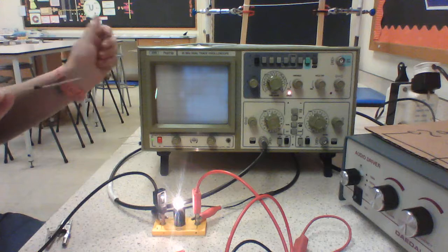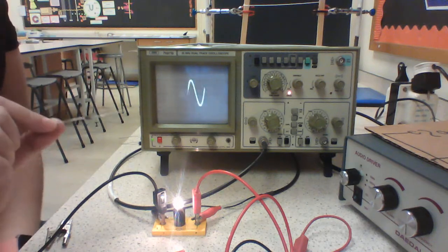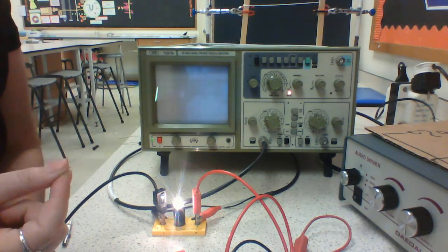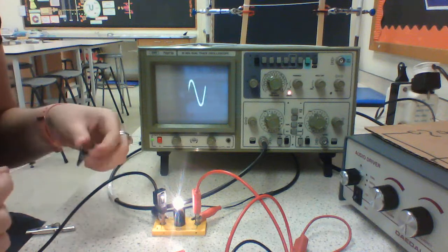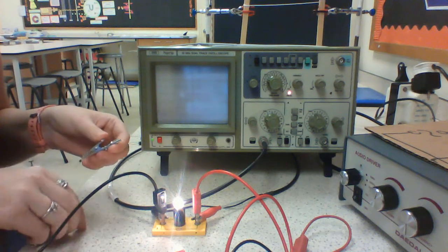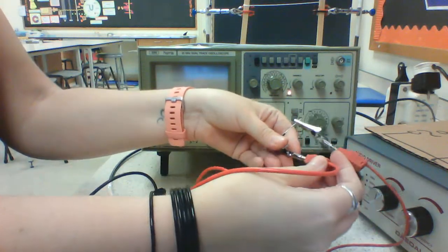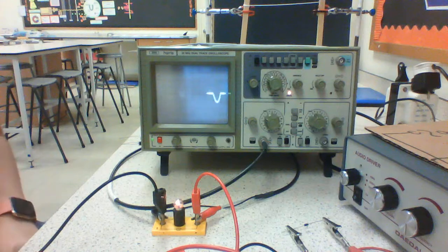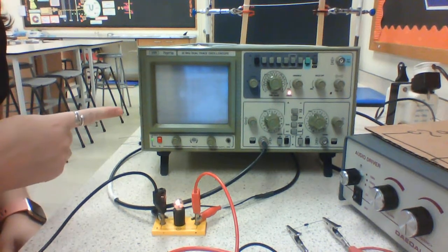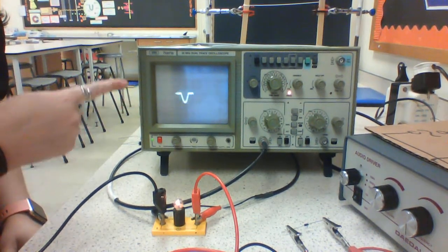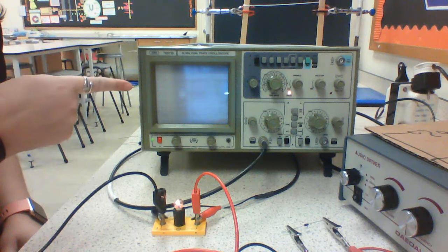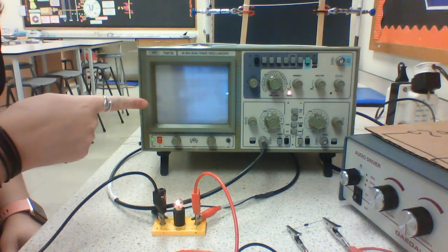I'm going to do a half wave rectification with a single diode. With a single diode, it goes in series with the load. I will show you the circuit once I've connected it. But hopefully you can sort of see the new path. I'm no longer getting an up and down motion on this, with the diode in the direction I've connected it. I'm just getting the down.